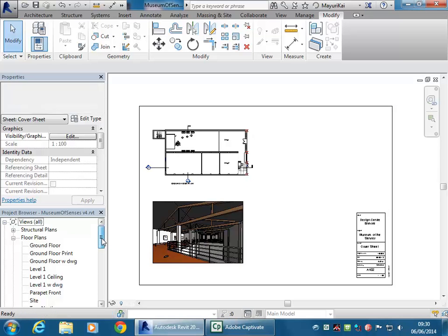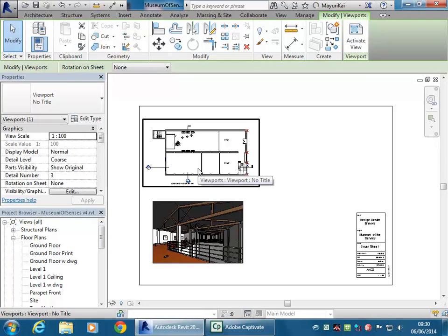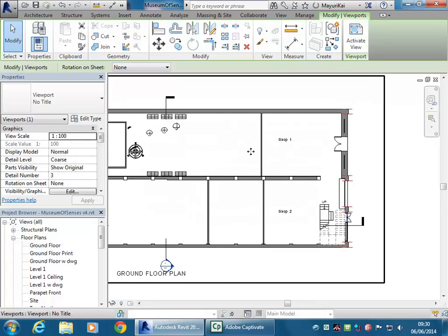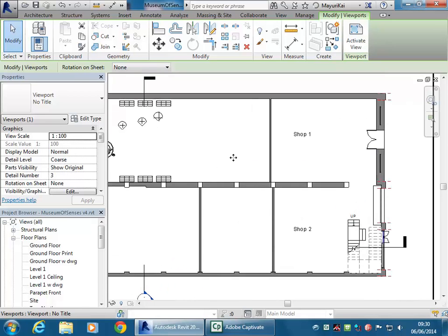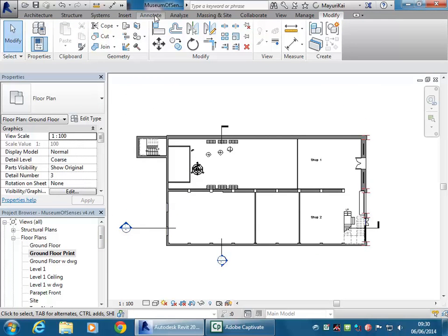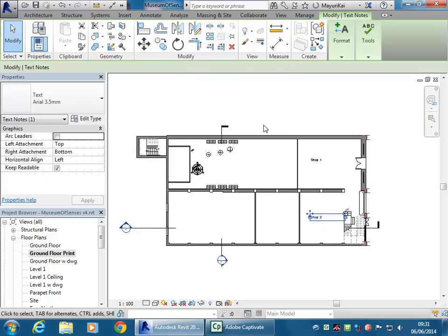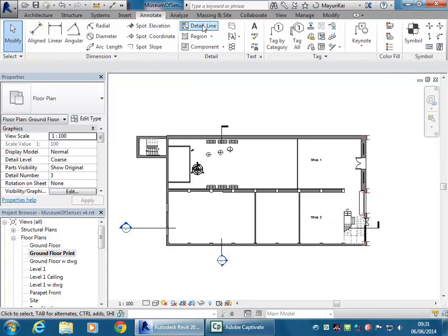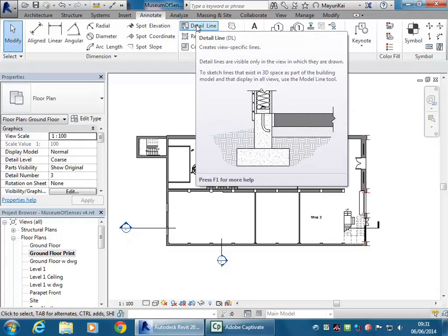So I should just show you a couple of final things. So far you've been trying to, I'm sure, model most of what you're designing in 3D, which is a good approach, but also you want to have quite often things shown in your plan that maybe you don't know how to model in 3D or are just causing problems for you. So just remember, you've always got the option of drawing in 2D over the views. And so if I go to, well, I'll just open that view up again. So I'll make it clear to you that when you're working with things like text and dimensions, and then also this new thing I'm going to show you, I don't know if you use detail lines, I mentioned them previously, but it was a while ago.